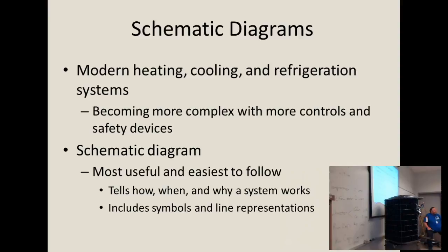Contact. L1, T1. That's right. L1 will be incoming from L1, and T1. L2 would be from L2, and then across from it would be the T, right? L's mean line side, T's mean the load side of the contact. Did everybody get that one?